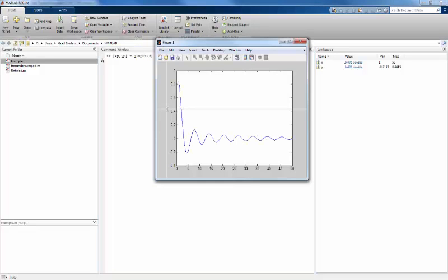When I hit enter, you'll see that the figure just pops up for me automatically. I didn't even have to click on it to bring it up. And also notice that my mouse is now a crosshair. Now what this means though is that MATLAB is not tracing the line. So if I clicked way up here, I would get a value of about 0.8, while our real value is down here in the negatives. So what this means is you have to be very accurate with how you're clicking on these points here.